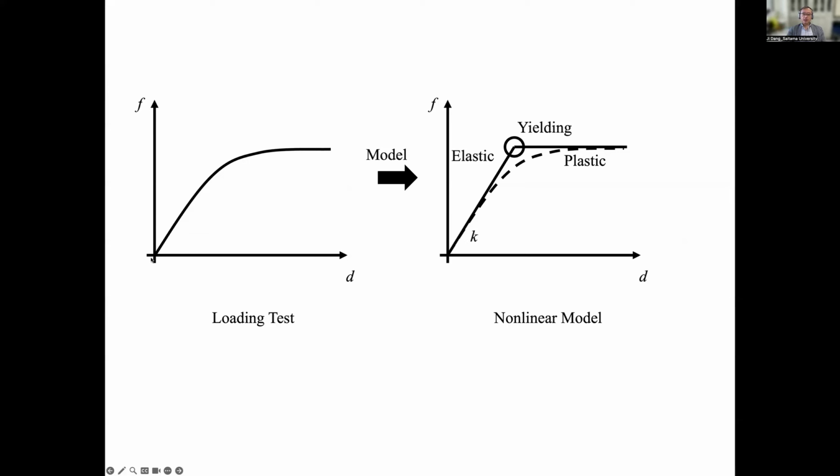So we would like to see a curve that increases, at some point yields, and then the whole cross-section yields, and the force and displacement relationship gradient becomes lower and lower until it is horizontal. This phenomenon we call yield. So in yielding structures, their gradients decrease. We call this softening of the stiffness.